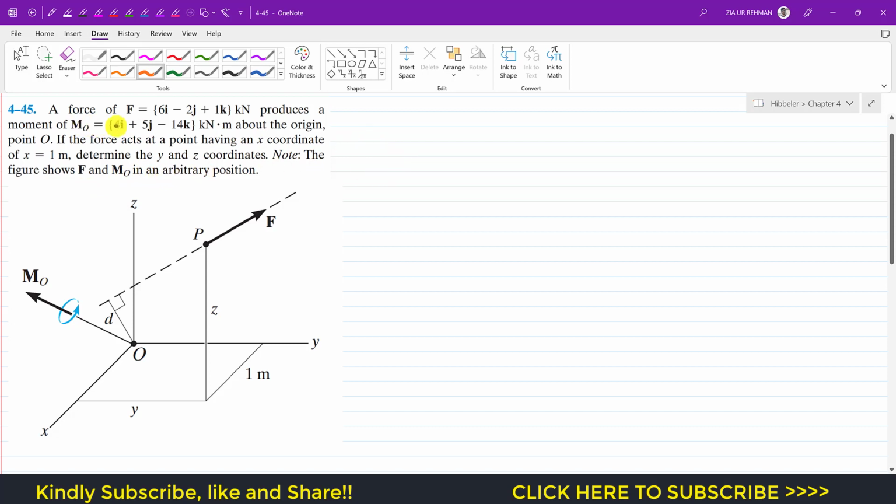So we are given the Cartesian vector representation of MO. We can write that MO is equal to the cross product of the moment arm and force. For this case we can define our moment arm from O to P. So this position vector from O to P is our moment arm. So we can say that MO equals ROP cross F. This MO vector is given, and that is 4i plus 5j minus 14k, and this is equal to this, right?